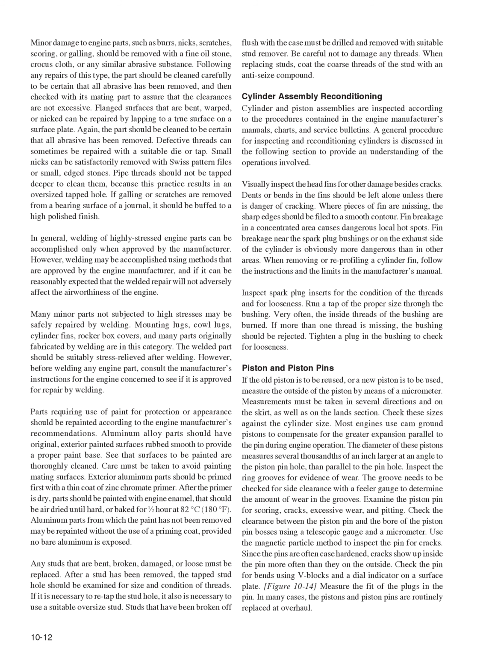Most engines use cam ground pistons to compensate for the greater expansion parallel to the pin during engine operation. The diameter of these pistons measures several thousandths of an inch larger at an angle to the piston pinhole than parallel to the pinhole. Inspect the ring grooves for evidence of wear.